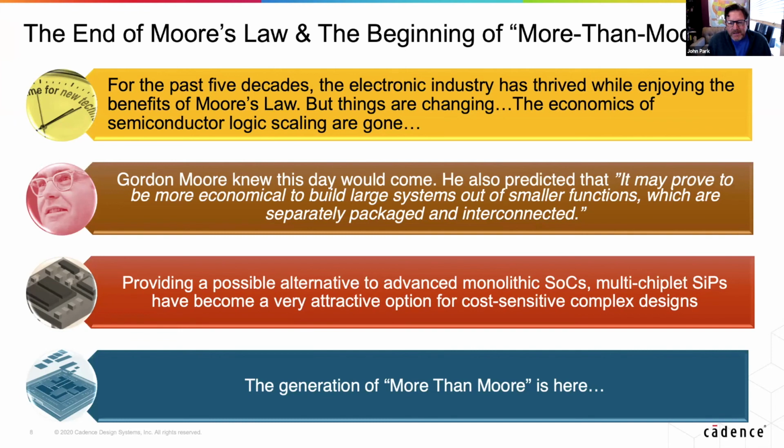Moore's Law is all about every couple of years, transistor sizes shrink dramatically, driving down the cost because I can put more functionality in a smaller space on the silicon. So it's really an economical model that said this is going to become more economically viable as time goes on every couple of years, because the cost per transistor will steadily go down.